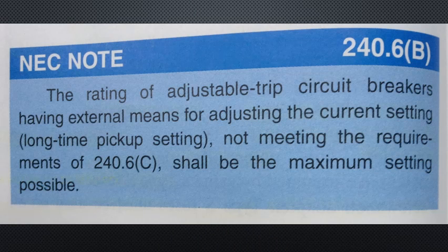NEC note 240.6(B): The rating of adjustable trip circuit breakers having external means for adjusting the current setting, long time pickup setting, not meeting the requirements of 240.6(C) shall be the maximum setting possible.